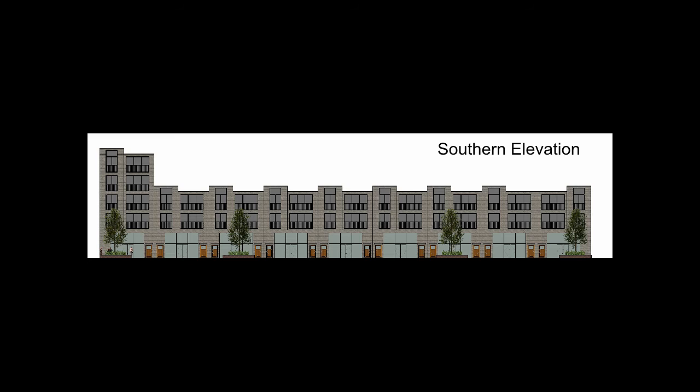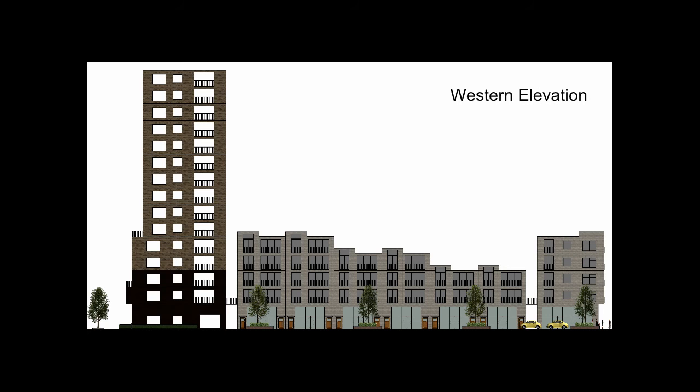Most buildings are up to 5 stories or lower to maintain human scale. The ground floor retail units have higher floor-to-ceiling heights to make it more usable and to make it easier to focus human attention to those shops. The corner plots have windows in the side elevation to provide surveillance and create active frontage.